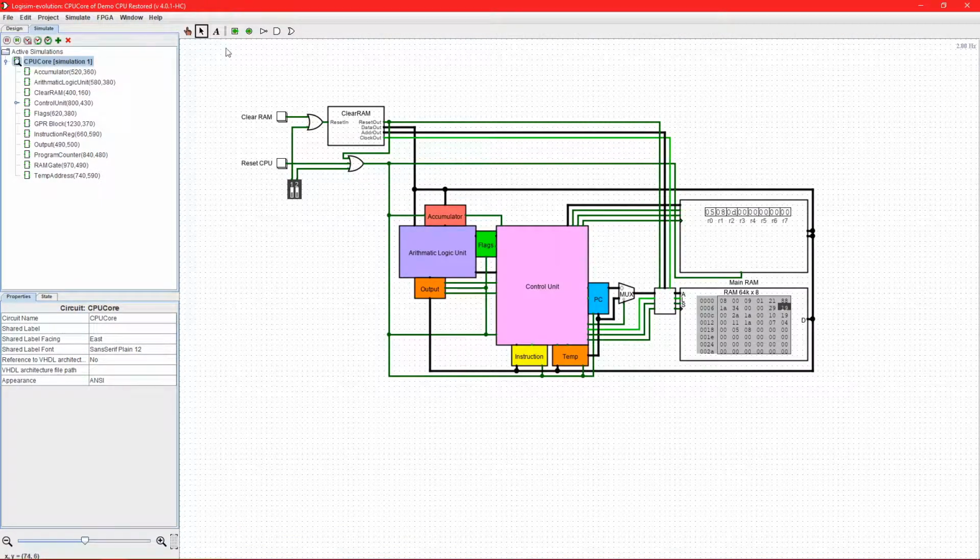What happens is when we load the temporary address register, we keep incrementing the program counter as we load the address register, and then when we finally load the data or store the data, the program counter is at the correct value to retrieve the next instruction. So we don't need a temporary spot to store the address of the program counter to. Instead, we simply multiplex the program counter with the temporary address register.